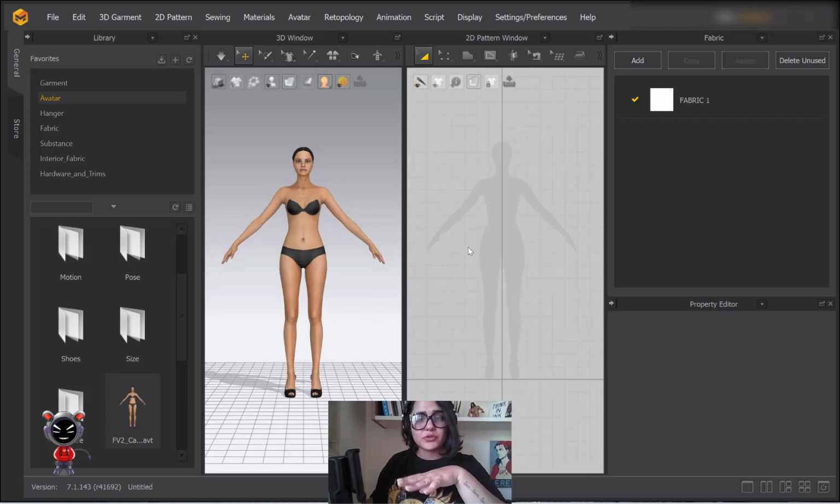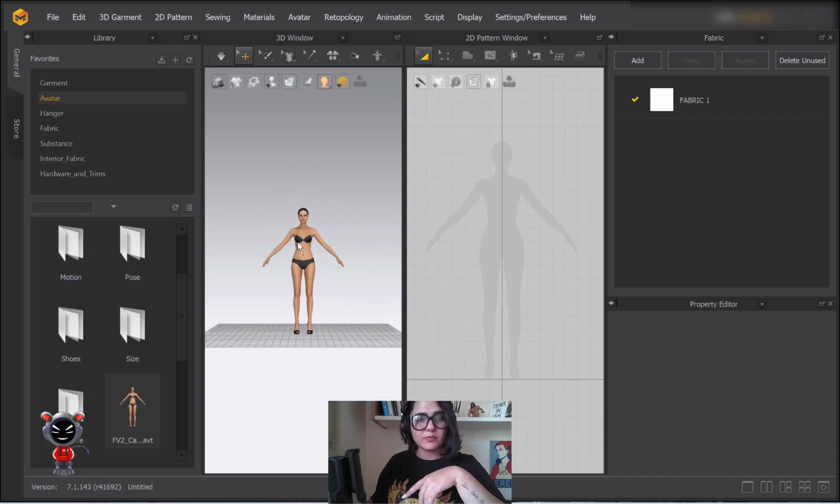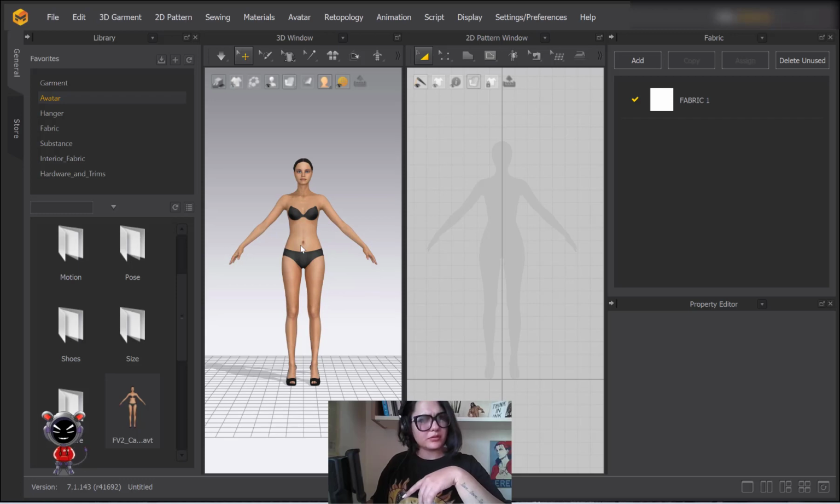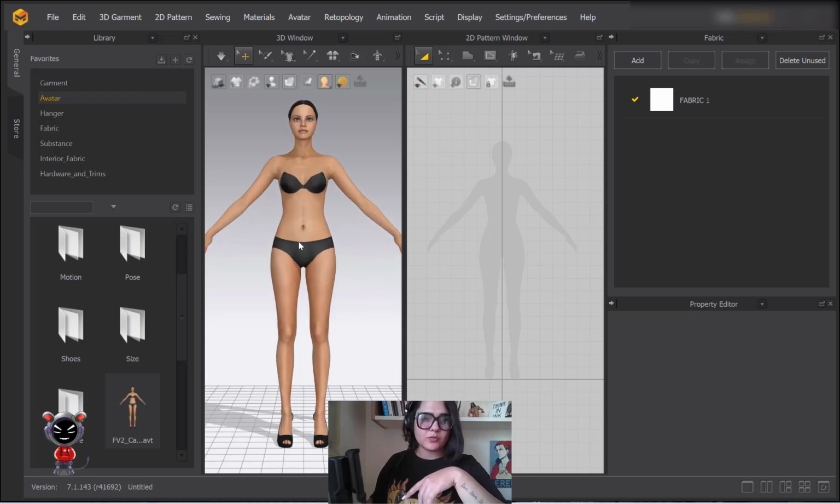If you choose your preset like me, like 3ds Max, I'm going to tell you something. On the mouse, if you scroll down, it will zoom out. If you scroll up, it will zoom in.